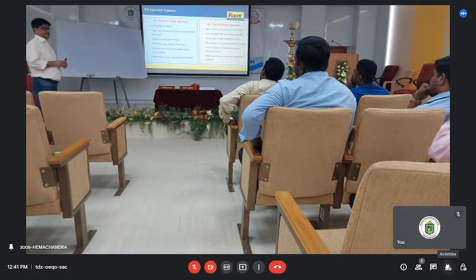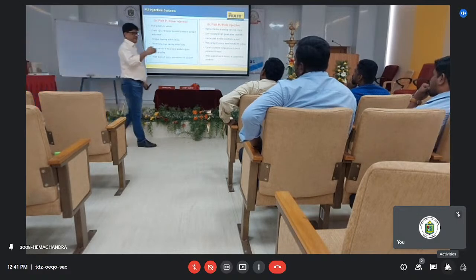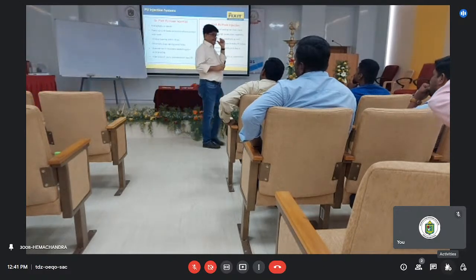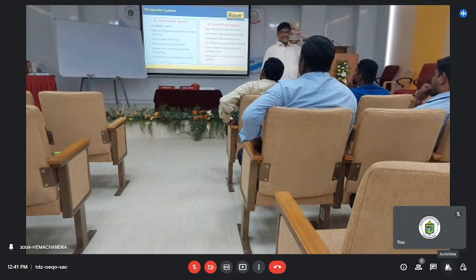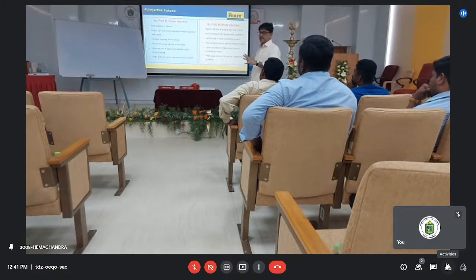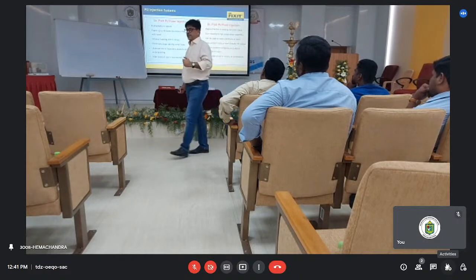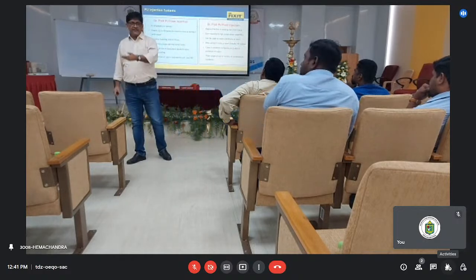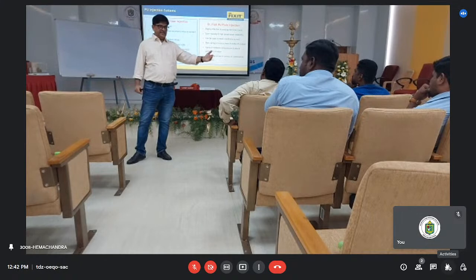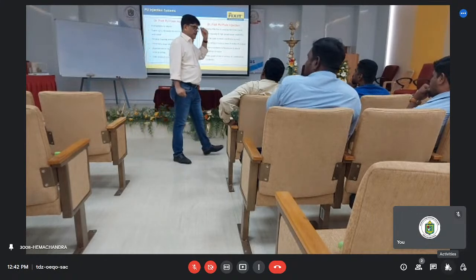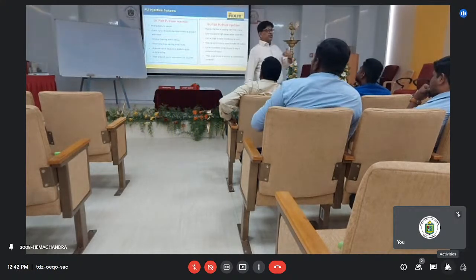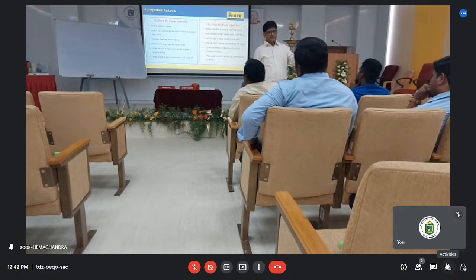A few PU injections are to be done for crack filling. Again, in these cases, when there is an active leakage and water is continuously coming, our process is first to do PU foam, followed by PU resin. People doing waterproofing often do only the PU foam and walk away. It has only blocked the water. He has not worked on the source or on the capillaries.